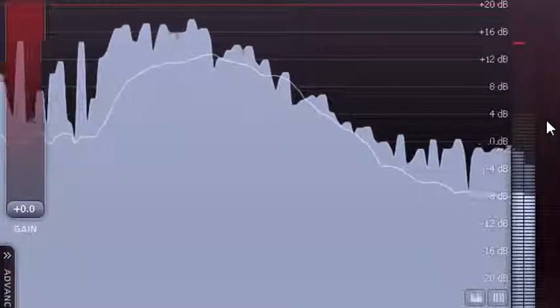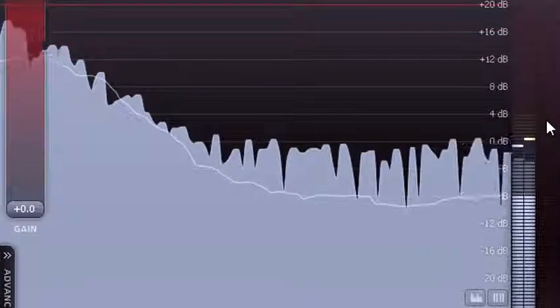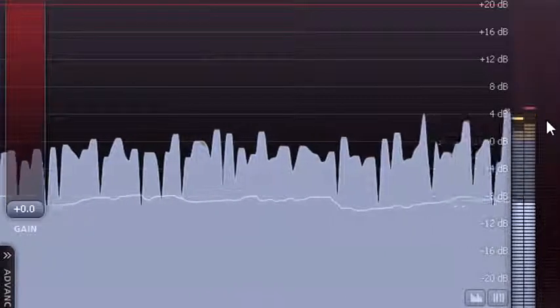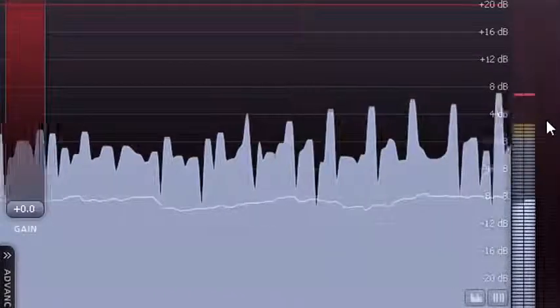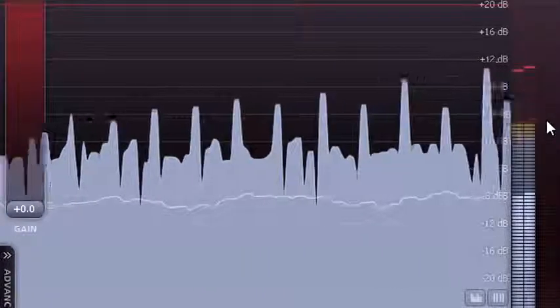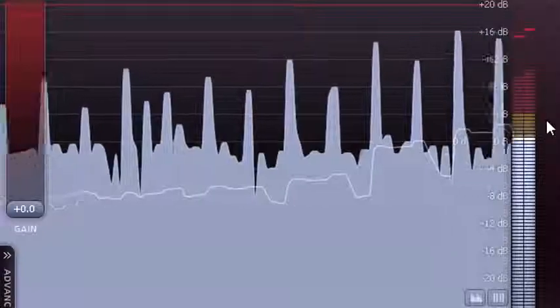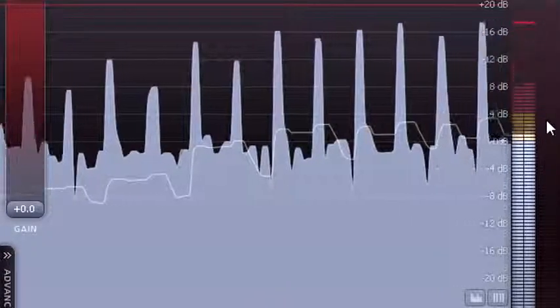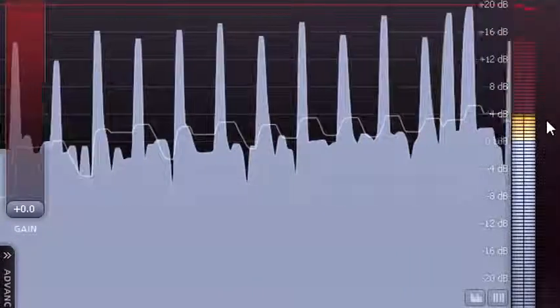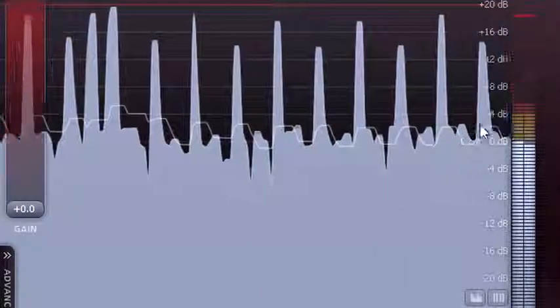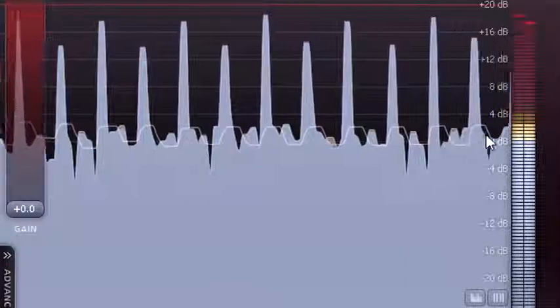This leaves plenty of headroom to accommodate peak levels, so the K20 scale is useful when you need to retain a very wide dynamic range, such as for a symphony orchestra, or a film soundtrack intended for cinema release. K20 is also a useful scale when dealing with material with a high peak to average ratio, otherwise known as a high crest factor, for example an uncompressed recording of an acoustic drum kit.